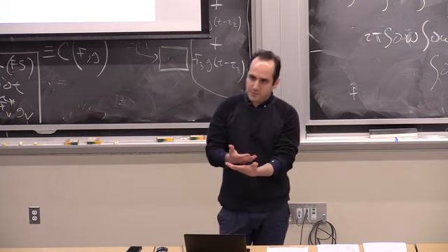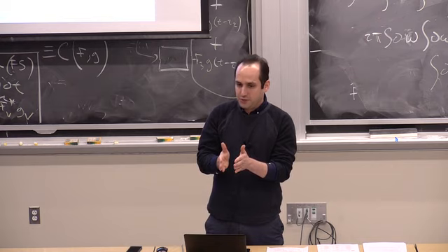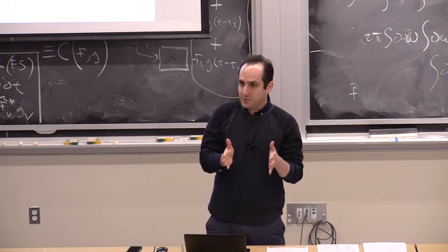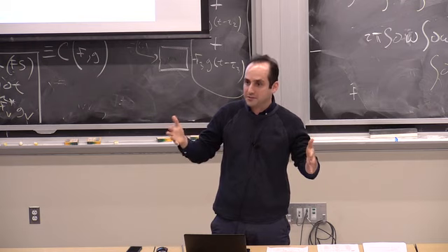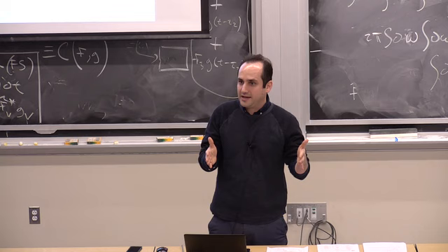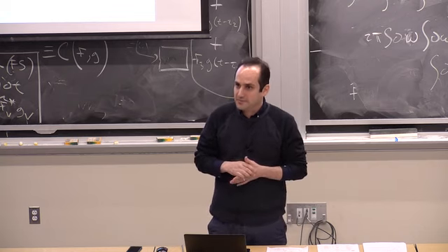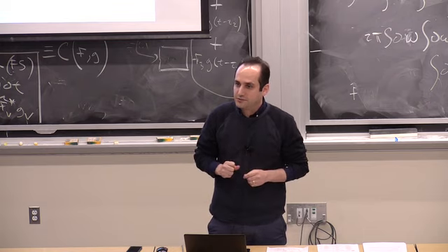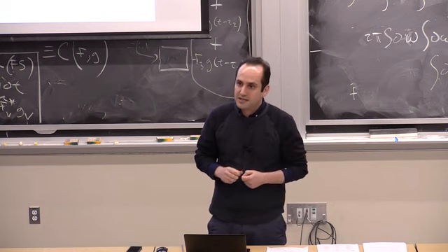So the reason that we would basically require more vehicles in balanced load is that for some of these headways, we need to stretch the headway in a way that it basically meets the balanced load on the other headways, right? And then once we do that, we may actually go over the maximum allowed headway that is basically trying to take care of maximum waiting time and level of service in the end.